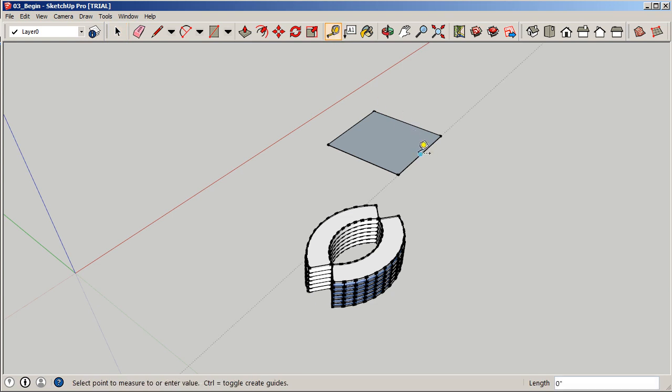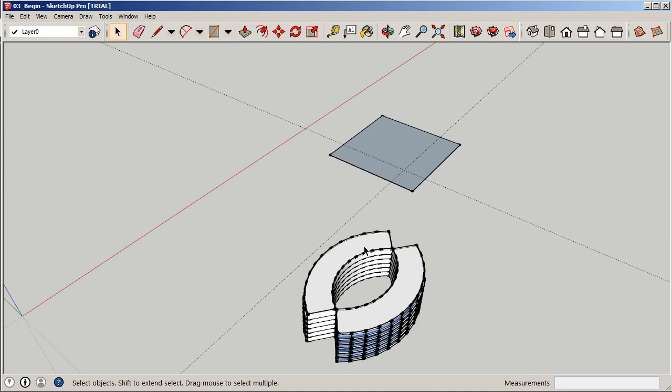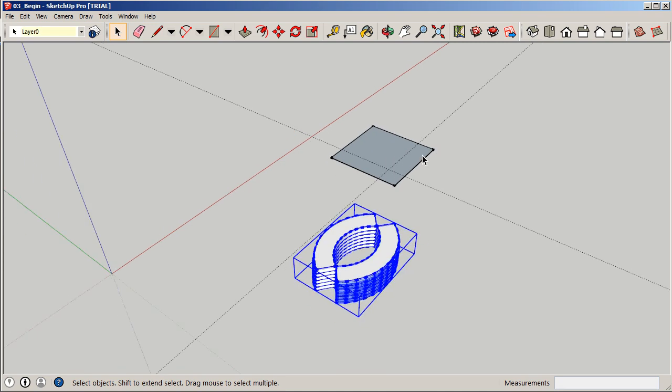It's that 75 feet by 75 feet. So in this case, we know we're working by 10s, so let's go ahead and make that 80 feet by 80 feet. So we'll say 80 feet. And what I mean by working by 10s is once we start working with this grid surface, you can actually specify the size of each grid. We're going to go on 10s, which is the default, but you can easily switch it. But it's important to keep that in mind as you're modeling this, because it's going to make laying out all your important elements a whole lot easier. So we're moving in increments of 10, so just keep that in mind.